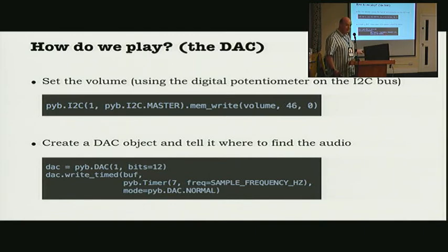Again, this is a blocked method, so if I have audio in my board, I just point it to the buffer and sit back and the audio gets played out for me, which is cool if I don't want to have any interaction or anything more sophisticated. Again, you can also write manually to the DAC.